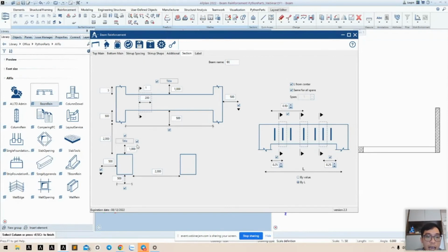And as you can see, we have the ability to set the width of the section here, and the name of the section here. The name of the section will start from the number or the character we type in this box. For example, we type here 5. The sections will be created as section 5, 5, 6, 6, 7, 7, etc.